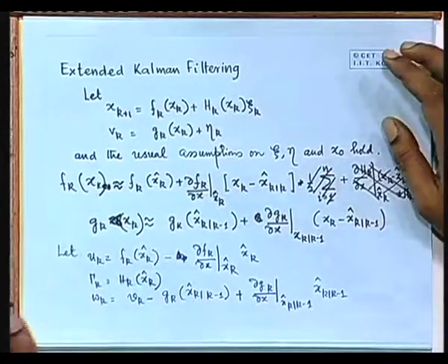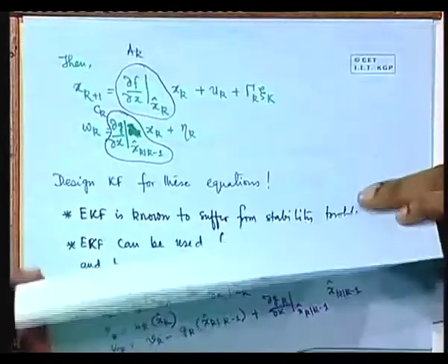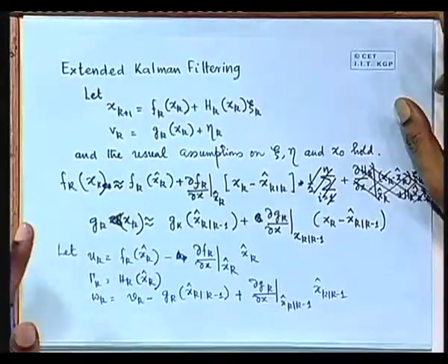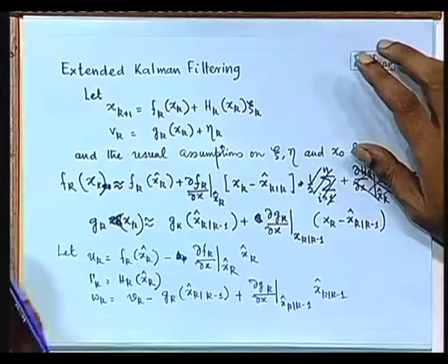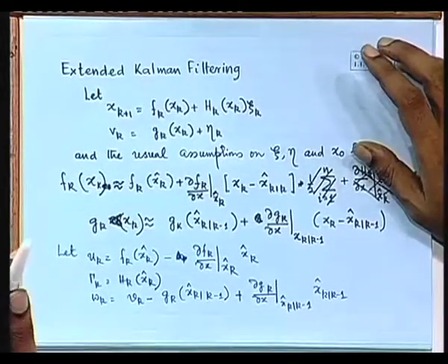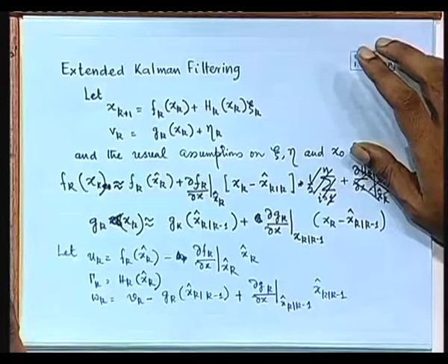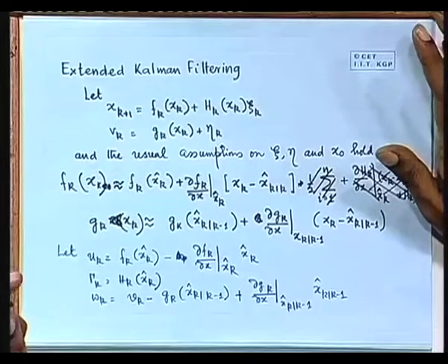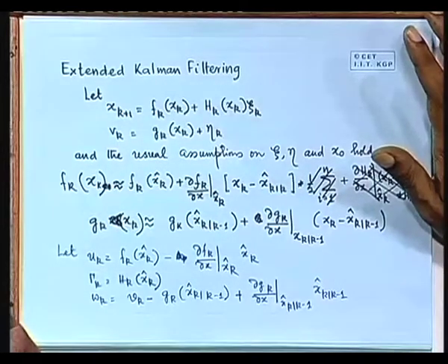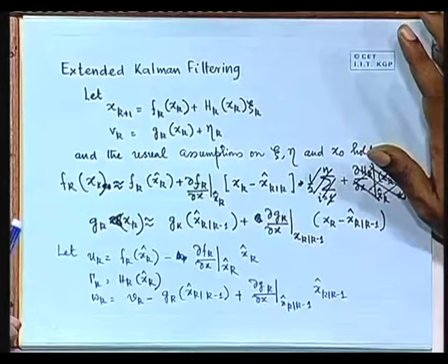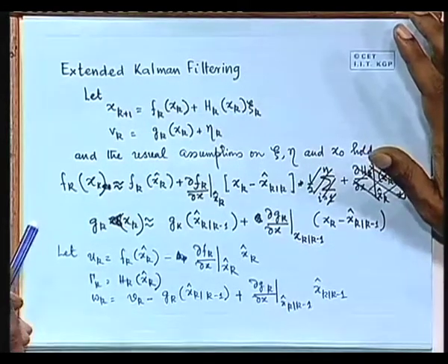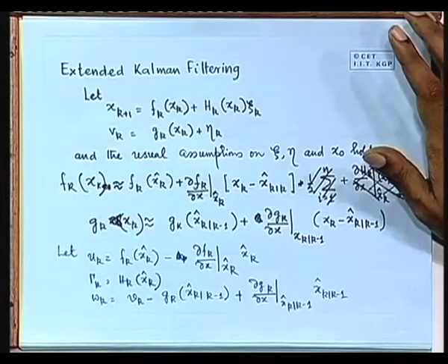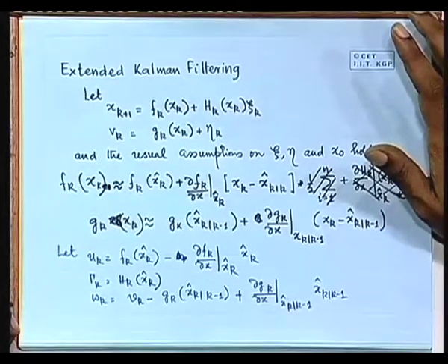To end, we want to just have a look at extended Kalman filtering for two reasons. Firstly, a large number of estimation problems, especially in aerospace, often turn out to be nonlinear. You see, we obtained a very nice linear model because we assumed that our measurement is in Cartesian coordinates. If our measurement was in polar coordinates, as happens often with radar, all our equations in theta and r would have been nonlinear differential equations, not linear.